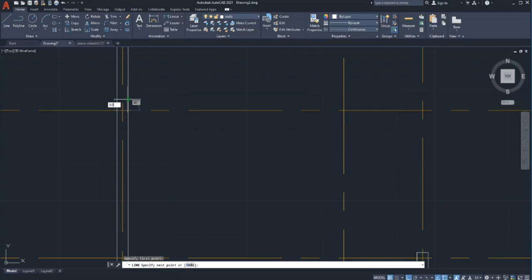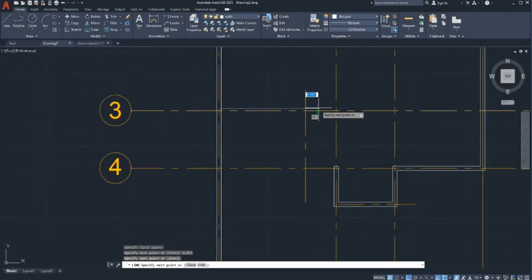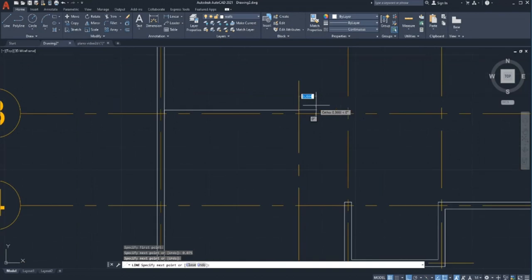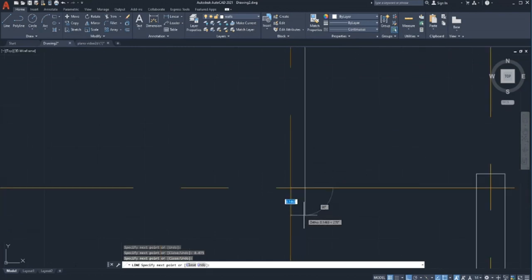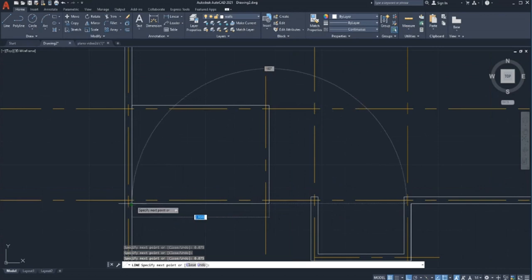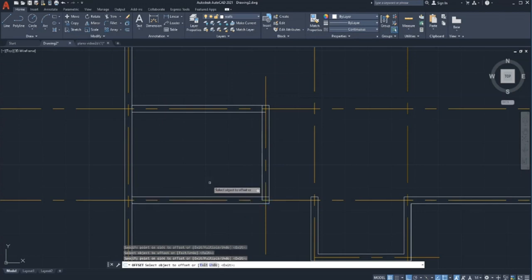Once we get the reference axis, we can start by drawing the line segment until a specific distance is reached, like this. Let's close this geometry, and then we can use the offset command and then the trim command to make it a closed region.